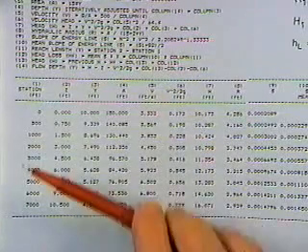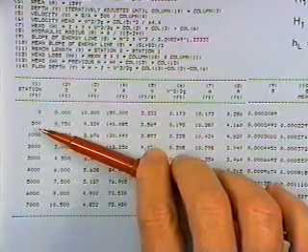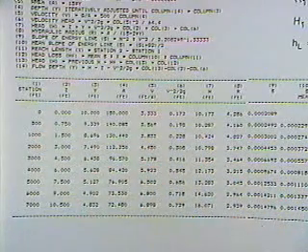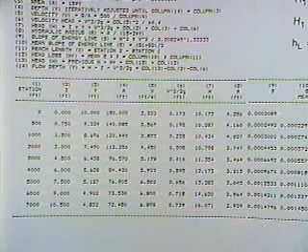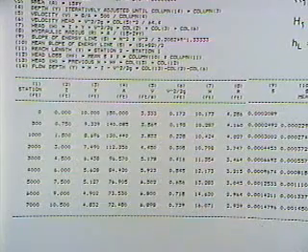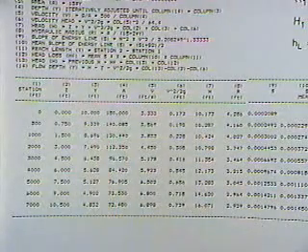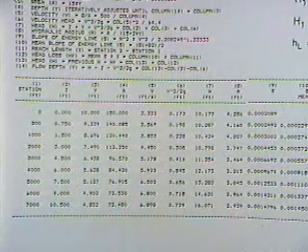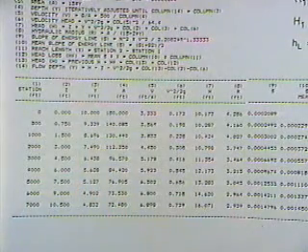And so what we do here, we set the stations. That's the difference. The different cross-sectional locations are set at the beginning, and we've got to know a starting condition. And we know that from the problem statement. The river into which the channel is flowing is at a depth of 10 feet. So given the 10-foot starting elevation, we can run through the computations.